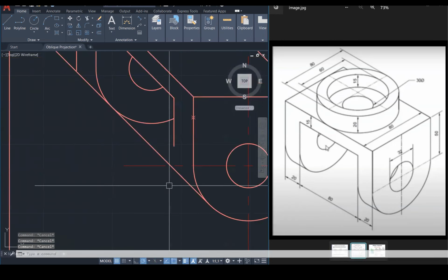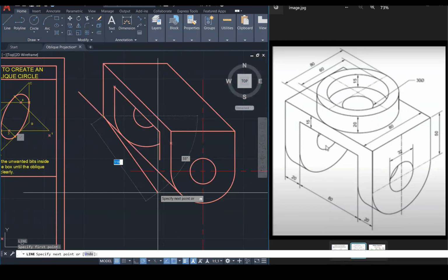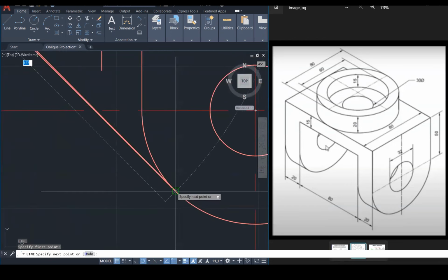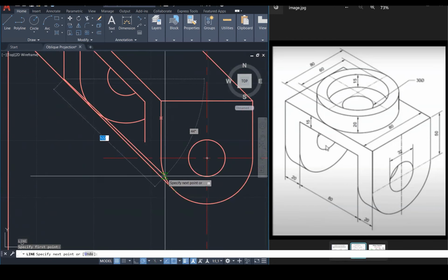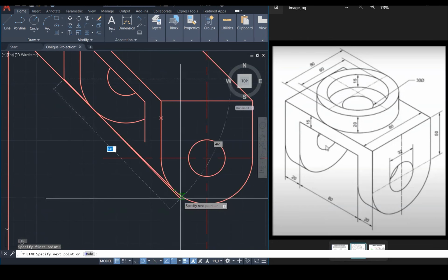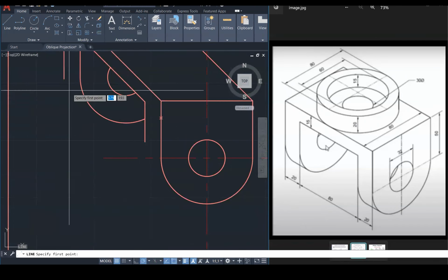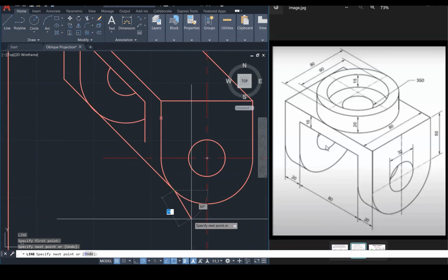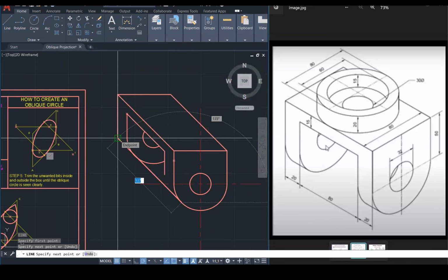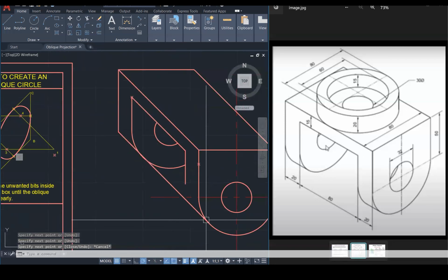So when I'm having problems gaining a tangent, I normally start from an outside point, find the tangent onto the circle. It indicates that you're drawing the tangent, and you see the circle. So let's erase this. Line, start from this outside point, and I'm looking for that tangent indicator, which is right here. And then from here, I pull it back to that point. Yeah. So I can see that this is in tangent.